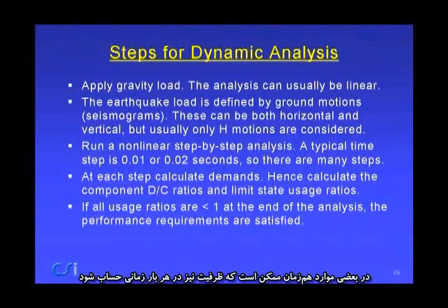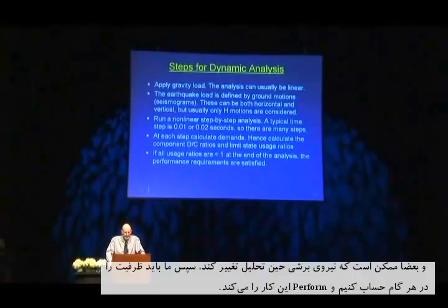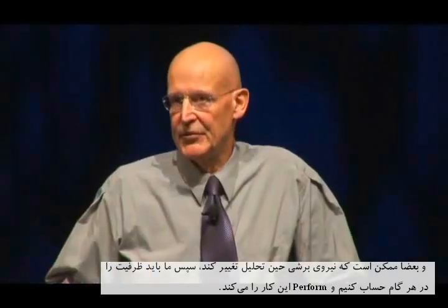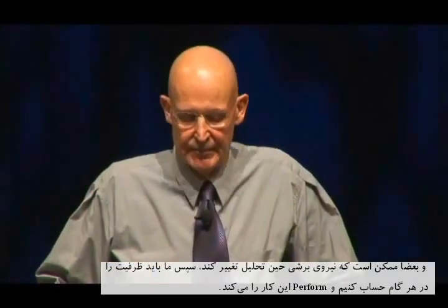In some cases, incidentally, the capacity may also have to be calculated at each of these time steps, because, for example, a hinge rotation capacity can depend on the shear force of the hinge. The larger the shear force, the smaller the ductility, the smaller the rotation capacity. Since the shear force varies during analysis, you have to recalculate the capacity at every time step also. And Perform can do this.